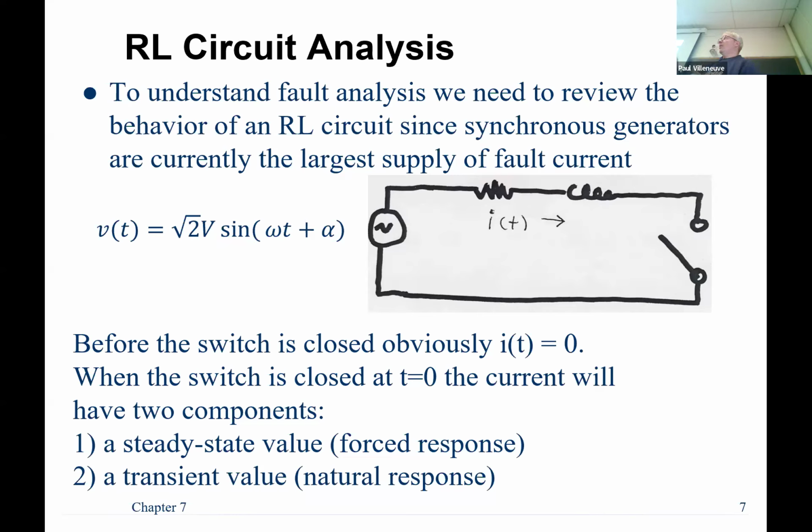It can't do it. So what you do is put a fuse in series with the contactor, and the fuse will interrupt the fault current, and the contactor can stay closed. There are devices specifically designed like that, called motor starters, that have a contactor in series with a fuse. That's how they remove or isolate faults. They let the fuse take it out.